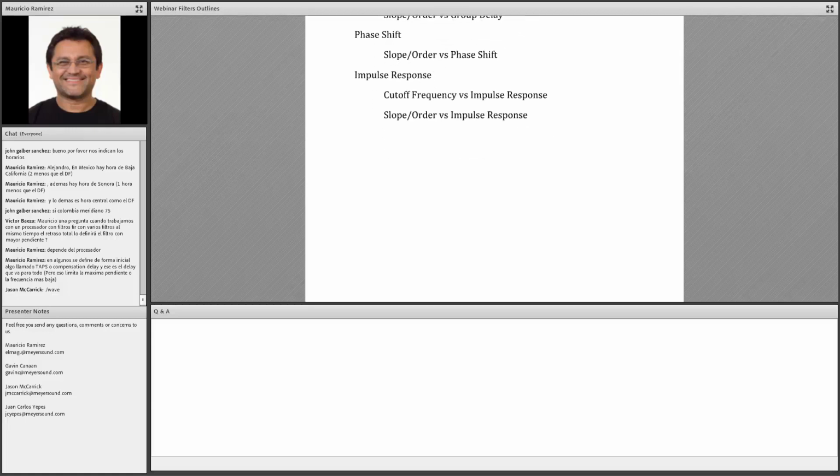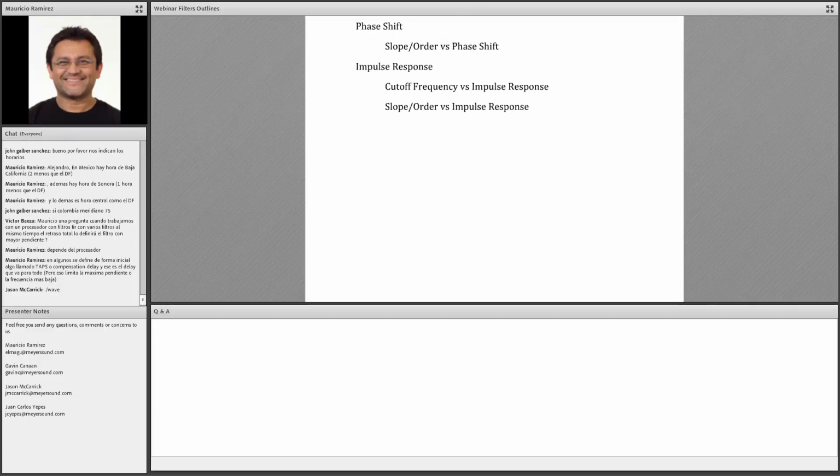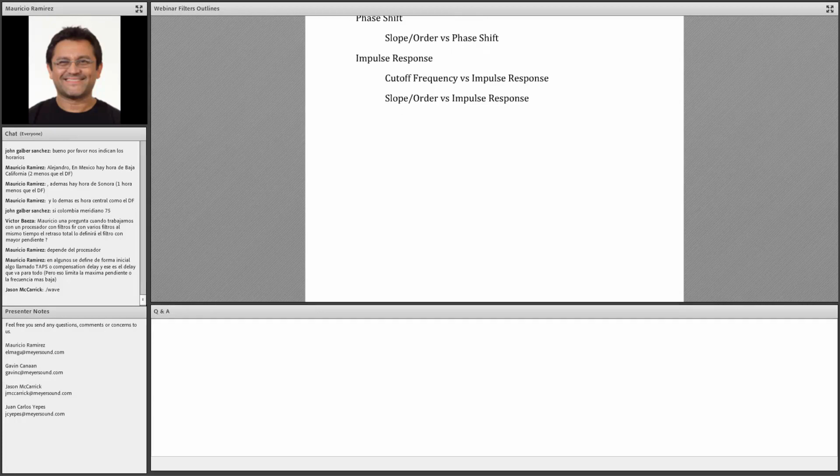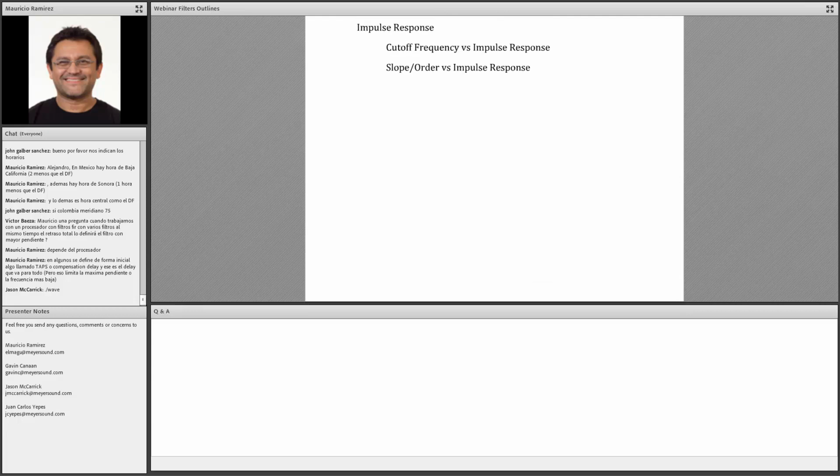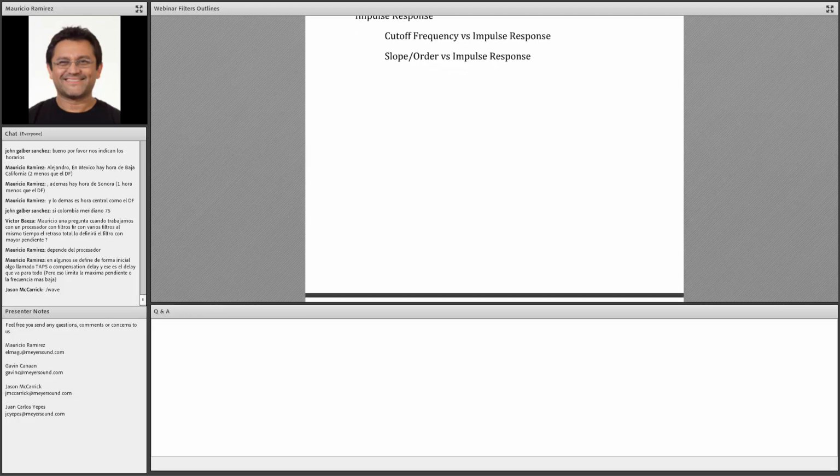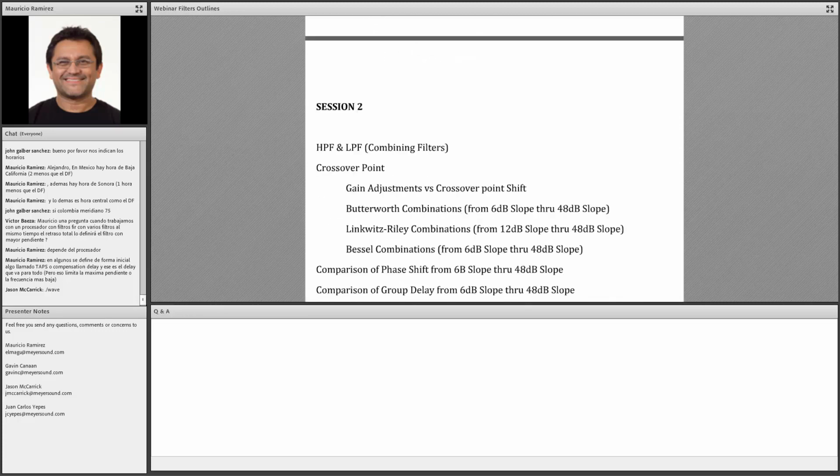Then we will view the delay in the common analyzer that you may be using these days, and we will use a phase display to understand the group delay of filters. And then we will use another way to view the information using what is called the impulse response. So we will view the group delay according to impulse response, that is a common measurement method in analyzers.